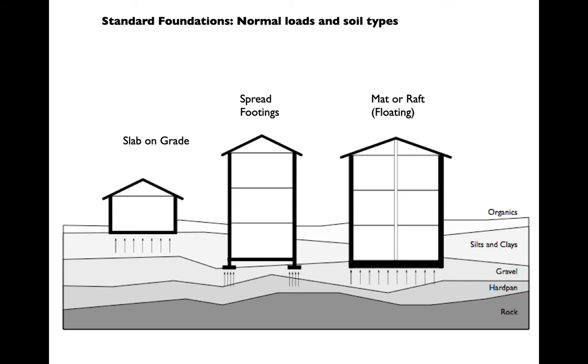In cold climates like the Midwest, we might want to go deep so that we get below the frost line. We don't have to worry so much about frost heaves. But so long as the whole building is on the same stratum, it may not be necessary, right? The building may ride up and down as a whole with a frost heave. It's only if we have different elements or different heights, different levels of foundations that we're worried about really getting below the frost line.